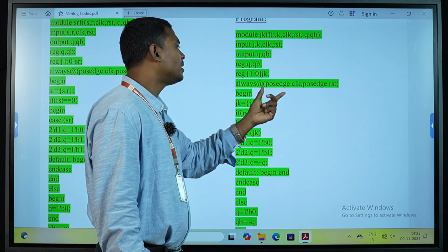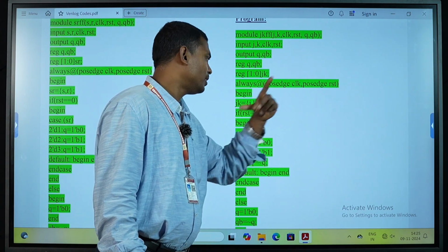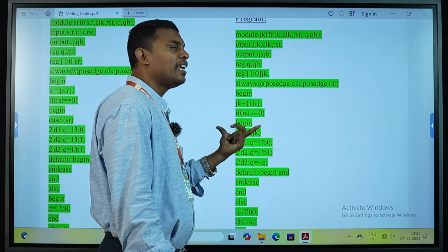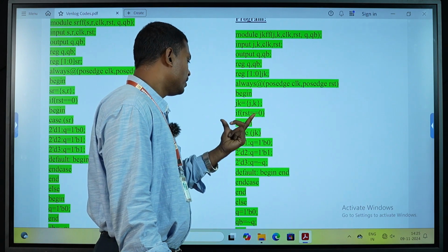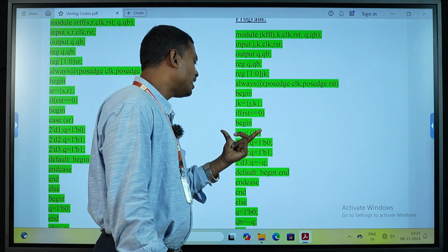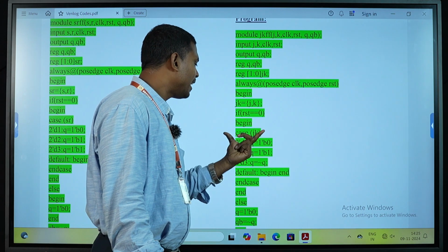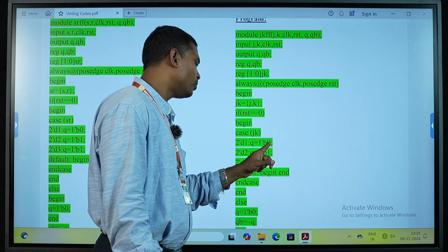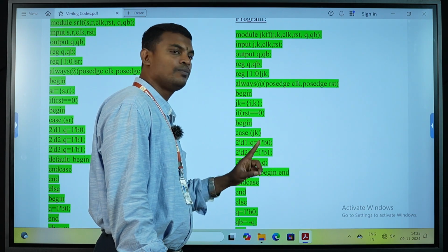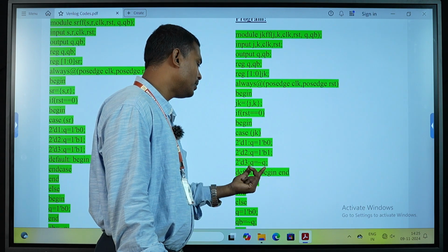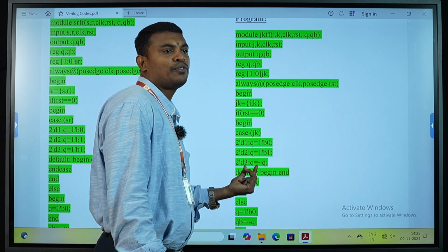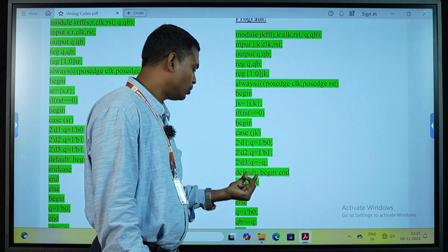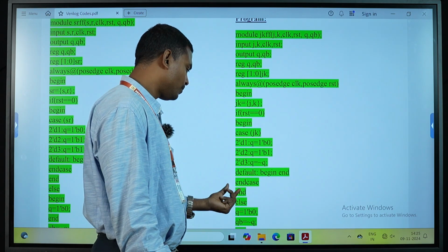And always it should start at positive edge of the clock and positive reset. Begin. Now for JK I am giving values directly as J comma K, and I am resetting my device here. After resetting my device, I am starting the case statement on JK, and I am declaring D1, D2, D3 values: first as 0, next as 1, and the last one as negation of Q, meaning if Q is 0, it should provide output as 1, and if Q is 1, it should provide the output as 0.